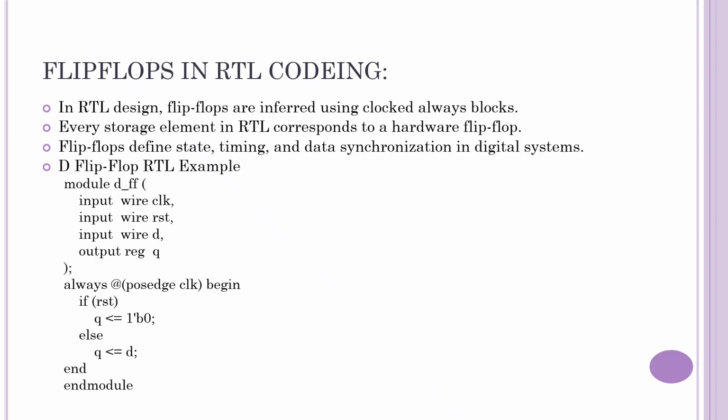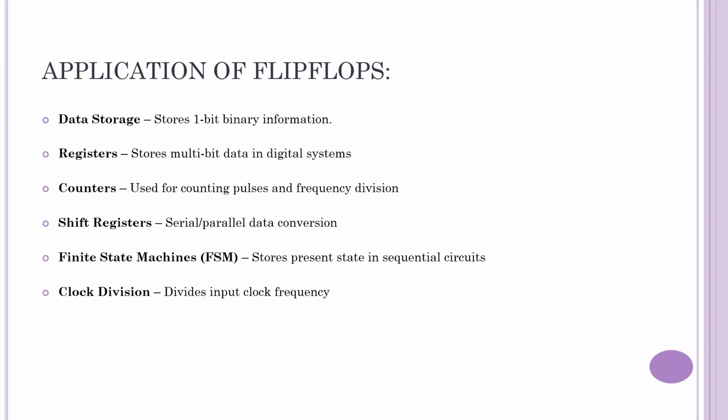In RTL design, flip-flops are the heart of timing and storage. Every always @(posedge clk) you write is a real hardware flip-flop waiting to be synthesized. Alright, now let's talk about where flip-flops are actually used. Because trust me, they are everywhere in digital systems.